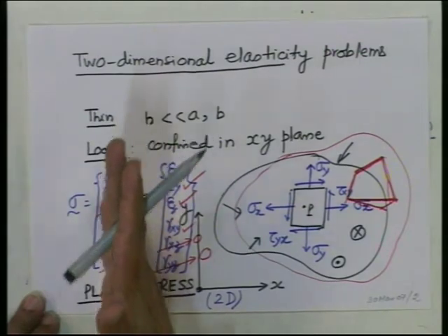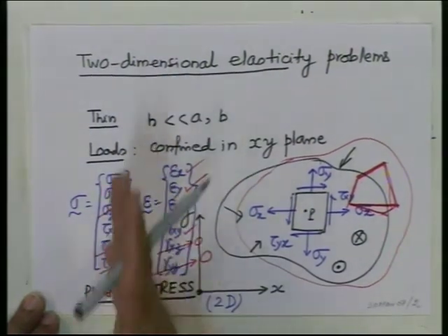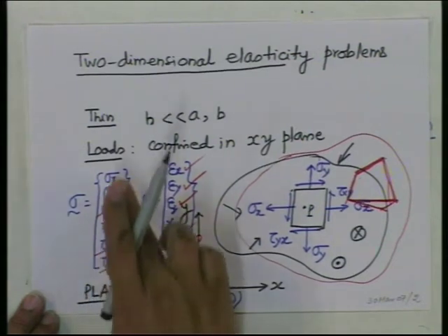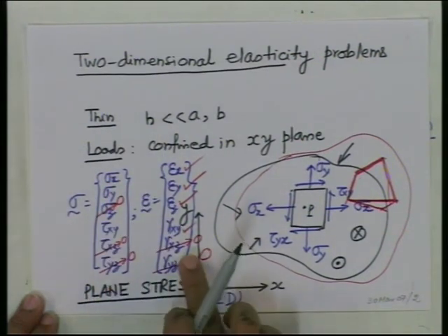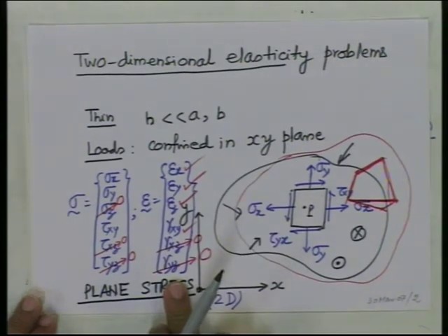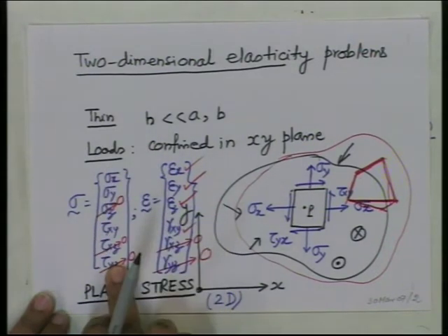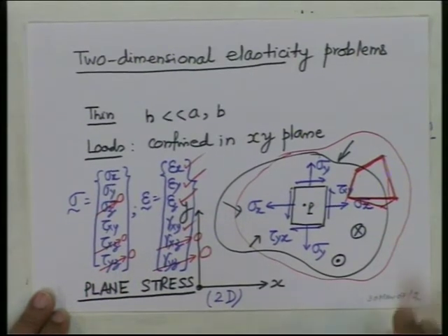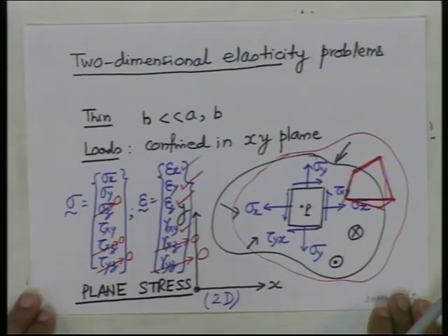When you start explaining plane stress, these are the two conditions. Then you write down this, and then you say what will be 0. Don't ever discuss strains first. If it is a plane stress, thin sheet of paper, you start with the stress vector. Don't bring in the word strain in your discussion when you are explaining this. So, this state of stress we call plane stress.